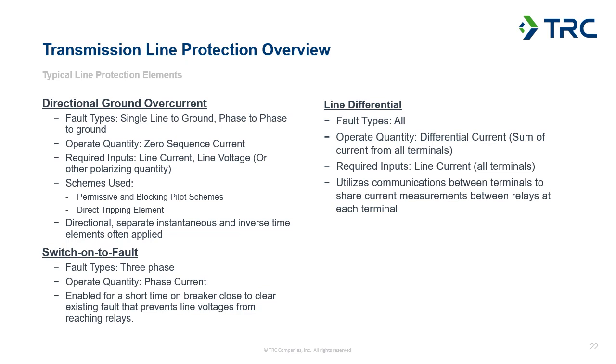So it's a unique scheme, really intended to catch the case where, after a transmission outage, the station closes in to energize the line, and somebody has forgotten to take the three-phase line grounds off. So it doesn't allow voltage to build up at the station because the station is effectively grounded once you close that in. So it's a very specific type of scheme to cover that case, due to that type of fault happening and not being cleared by local protection in the past.